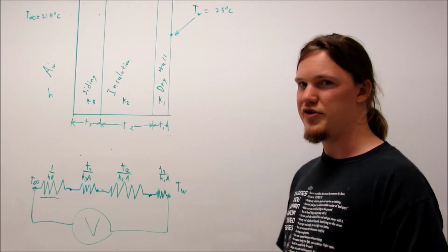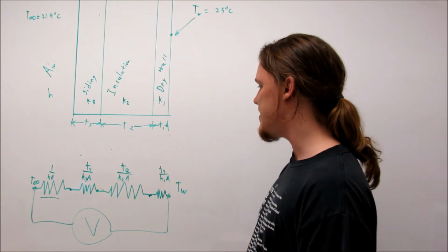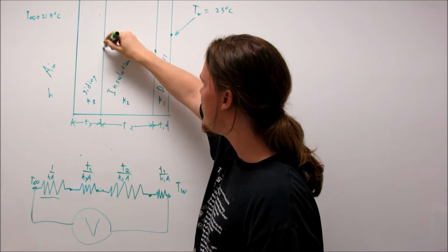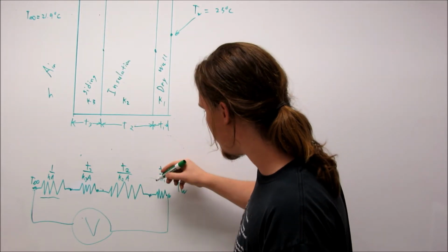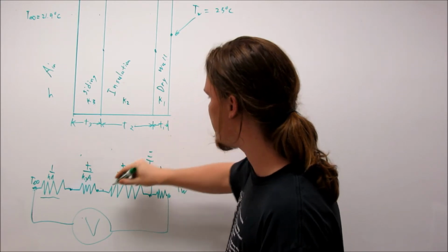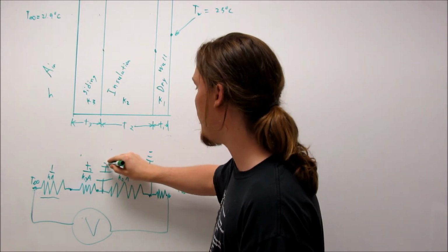To make it a little bit more interesting and useful to people that are better with electrical problems, let's look at a transient problem. The only difference we'd have to make is for each of the temperatures inside the wall, you add a capacitor to represent that temperature. The charge on each capacitor will represent the temperature at each point in Kelvin.